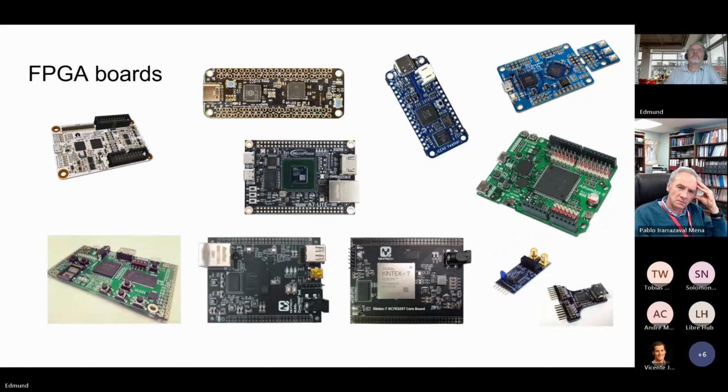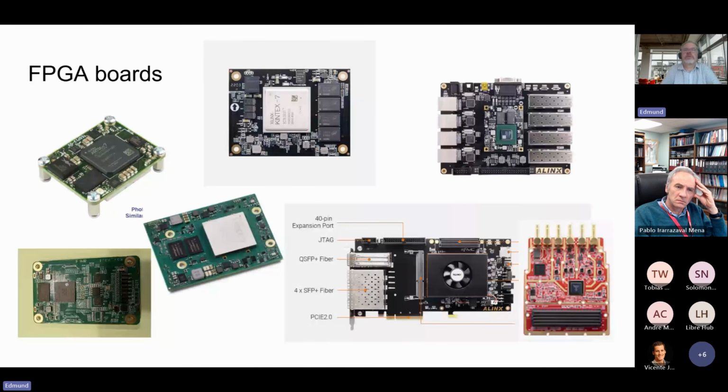The next category is the category of modules, where the FPGA does have a memory, usually a DDR3 memory, and that requires a large number of wires connected between the FPGA and the memories. And also for the power supply and for the boot up sequence. And those modules are available in different configurations from different vendors, and they are plugged into a baseboard.